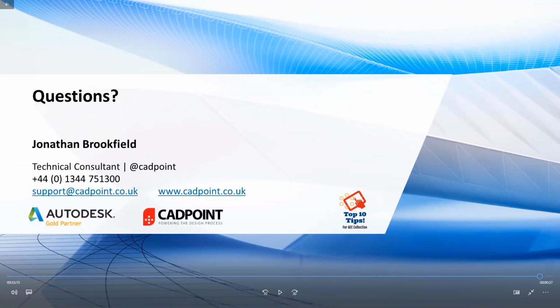But with Inventor you can customize any component you like. If you have a Revit library of items, or DWGs, these can be brought into Inventor and then brought into InfraWorks. But that might not be the best workflow. You might be better off doing your design, unless it's conceptual, elsewhere. If your detailed design model requires these kind of things, put them into your Revit model or Civil 3D model and then bring them into InfraWorks. Either way, there is a workaround for it.